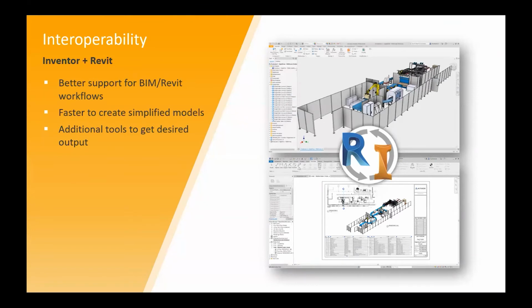We've got the option to export to RVT, which incorporates the new simplify command to produce a Revit model having only the components and features needed for the Revit design. A Revit exports browser folder is placed in the Inventor model. It's populated with a node for the exported model. As long as the model is maintained in the specified path, you can edit, preview, open in Revit or an associated application to update the Revit model.